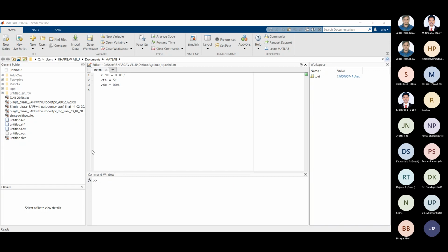So let's take our elements from the library. This is the library browser where we can find our elements, and finding the elements can be done in two ways. One, we can search here, or else we can go to Simscape, Electrical, and Specialized Power Systems. You can see here fundamental blocks, electrical sources, and this is our DC voltage source. One more way of searching for components is that we can directly search the component name, IGBT. I'm taking the 8 IGBTs.